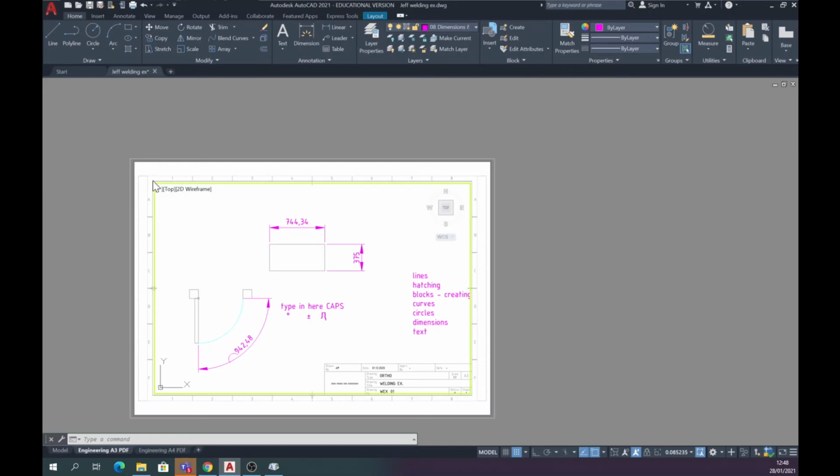Now, we spoke a little bit about viewports. We had this viewport. That's one viewport. You can have multiple viewports. I could have one viewport that is designed to accept drawings and dimensions which are at a scale of 1 to 30. But I can have a second viewport down here, maybe for a tiny item like the hinge on this door, and maybe I would set the scale in that viewport, which we've not created here.